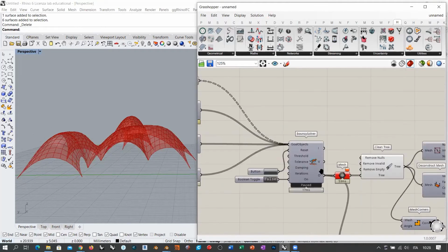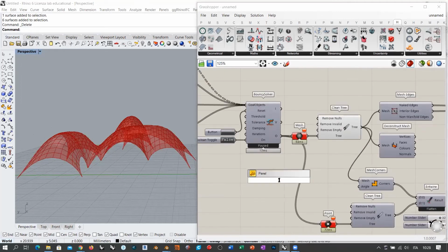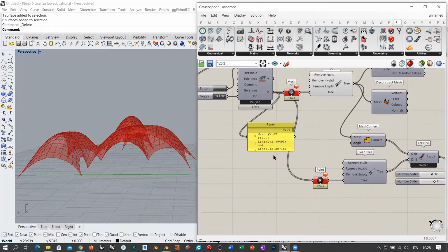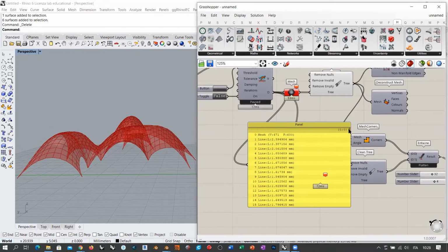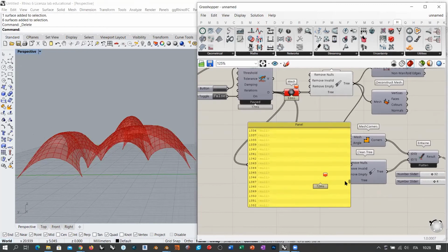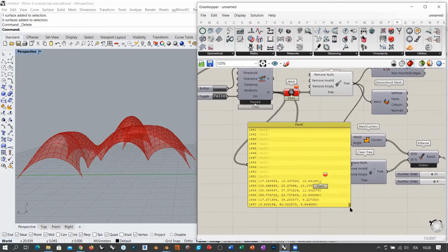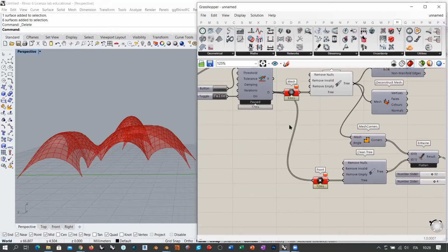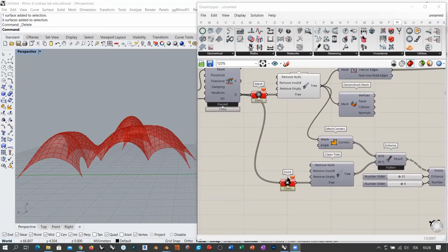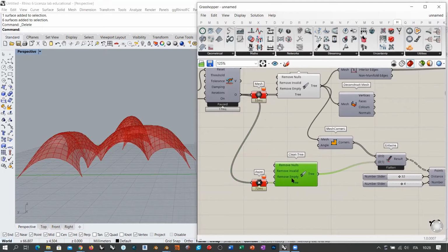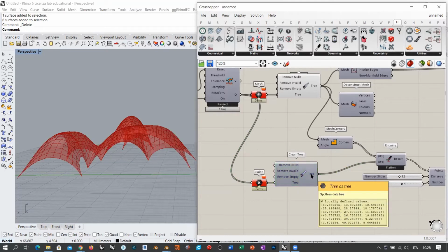And so if I do this, the output will also contain, if you remember, at first it contained the mesh, the lines, and then only null objects, which were the forces. But now at the end, you will find these 6 points, which are the 6 centroids from the original polygon, but now after the deformation. So you see that their z coordinate is now actually different from 0. Okay, and so I use the same method. I take a point container and a clean tree to obtain exactly the 6 points.